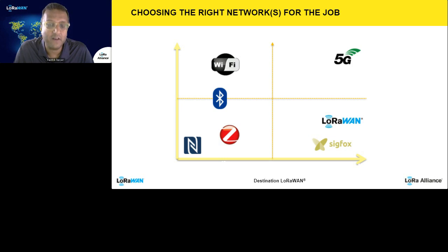It is not great, as we saw, for something that needs to traverse a reasonably long distance and something that needs to have months, if not years, of battery life. Moving down to Bluetooth and Zigbee, again, both of these are short range, a little bit better on the power side, but still don't have the reach that you might need for an application like this.